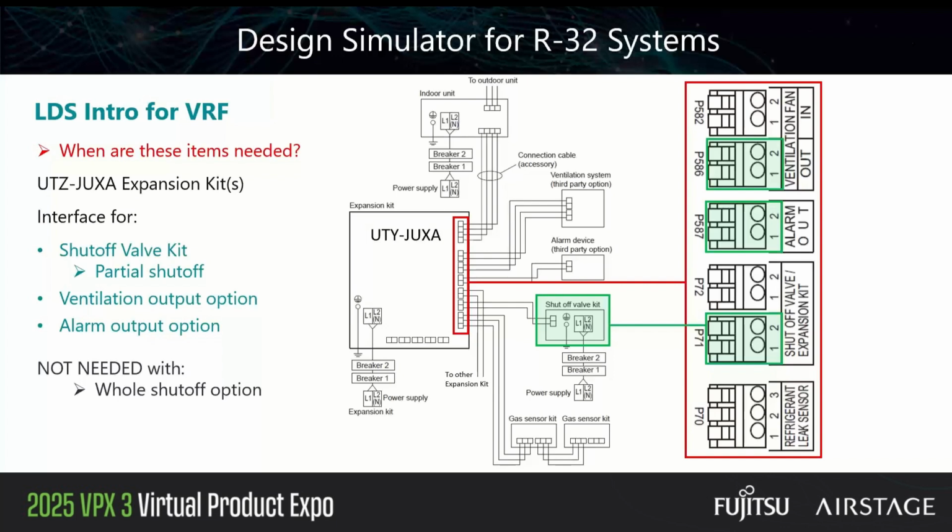Those of you that are familiar with our AIRSTAGE systems and external output use know that we have a 12-volt output with a 50 milliamp DC max holding current. However, that is exactly the same with this as well, so at least we remain consistent there. A very common relay that we use is a RIB relay, where the coil meets these load requirements.